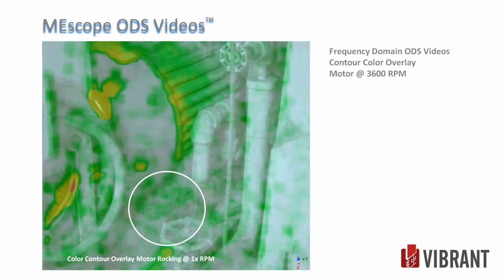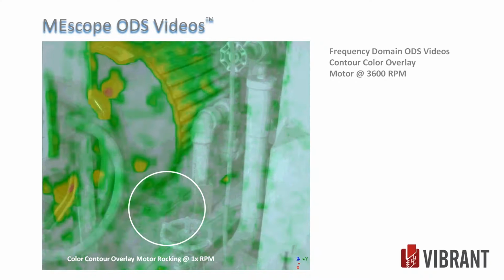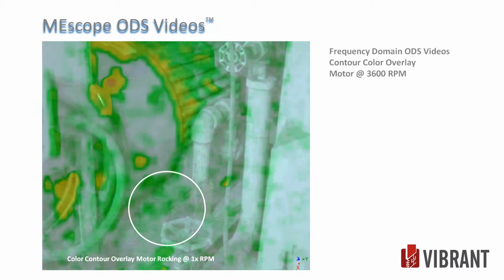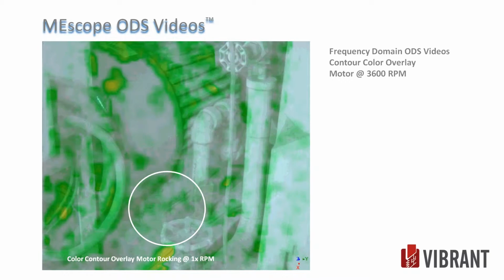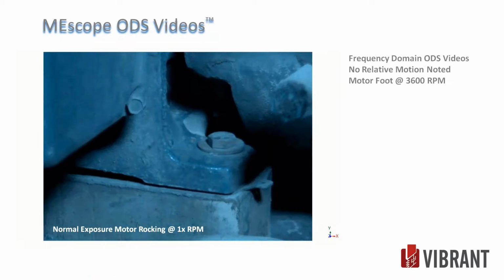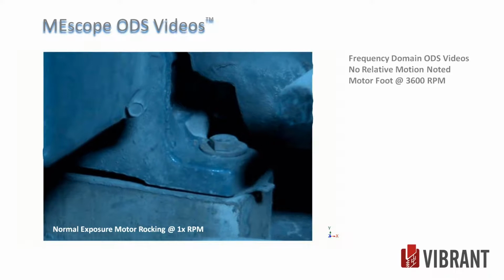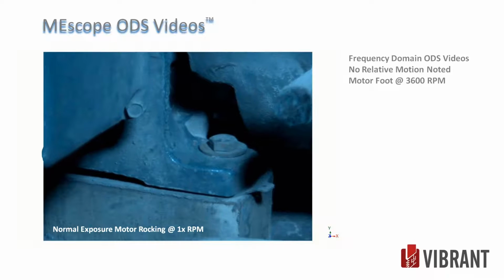realistic to what happens in machinery when you have a loose mount. You get very little motion in the mount, but it's out of phase, and the higher motion is higher up on the structure. So you're like wagging the tail. This is the close-up of that mount. So I got on my belly and crawled in there and got a good camera angle and shot this.